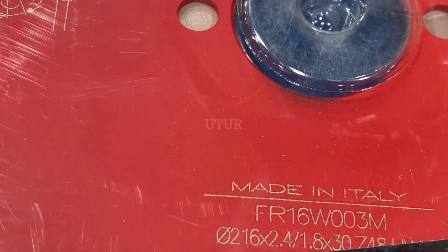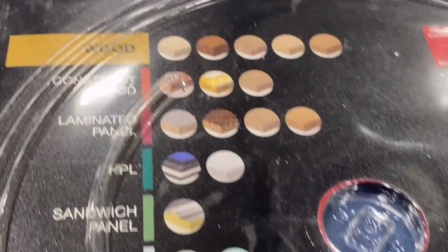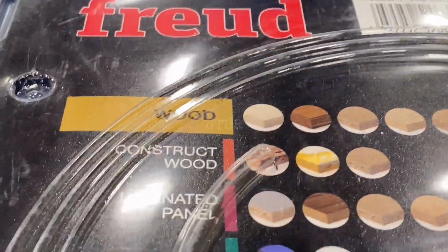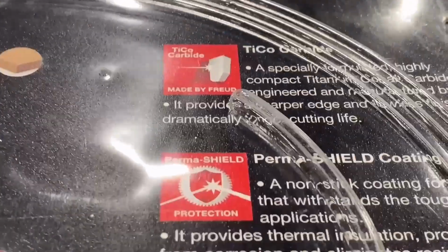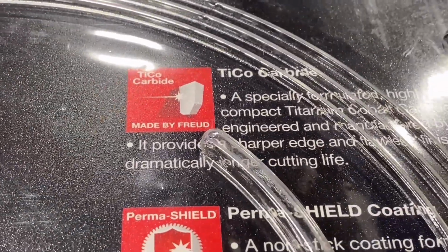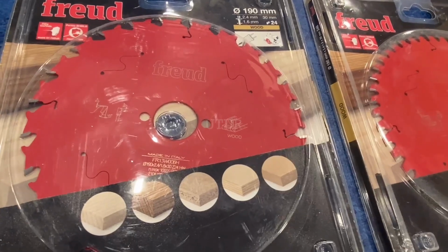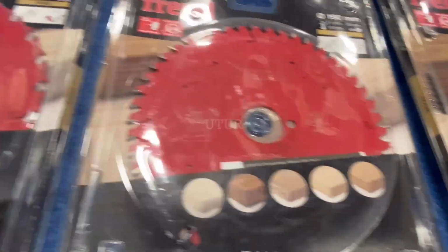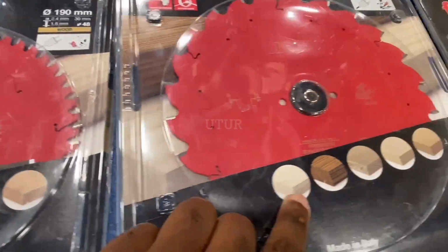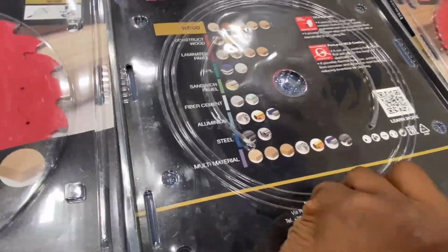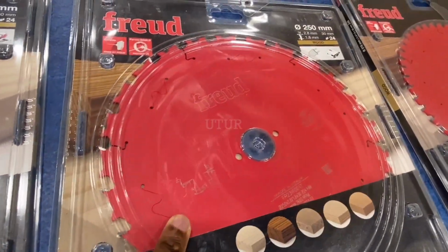All of the 5 quality blades displayed are specifically for working wood, as you can see on the reverse of the label where wood is highlighted specifically for these blade types. And you can also see that all blade types and teeth are made from titanium carbide. So when selecting your blades, apart from the type of material that you're cutting, take cognizance of the gullet sizes, the number of teeth, the hook angle, the bevel, and what your blades are specifically designed for, in this case wood.